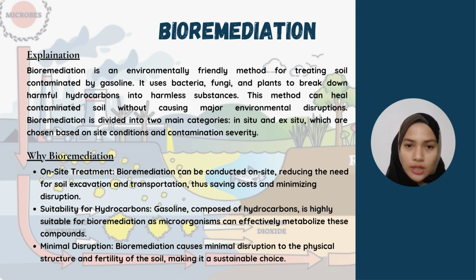I will continue the presentation, and I will talk about bioremediation. Bioremediation is an environmentally friendly method for treating soil contaminated by gasoline. It uses bacteria, fungi, and plants to break down harmful hydrocarbons into harmless substances. This method can heal contaminated soil without causing major environmental disruption. Bioremediation is divided into two main categories, in situ and ex situ, which are chosen based on site conditions and contaminant severity. Okay, why do we choose this method?